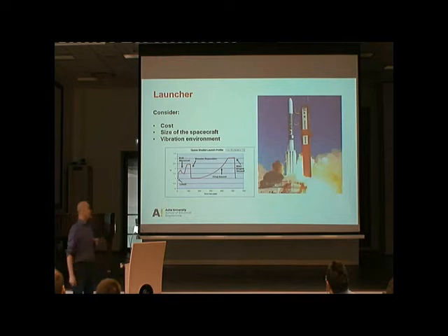Additionally, for these limitations in size and mass, you have also the certain environment. Different rockets have different vibration environments during the launch. So it depends totally, are you going with a Soyuz rocket or are you going with Ariane 5? If you go with Soyuz rockets, your vibration environment is 2-3 times worse than with Ariane 5.